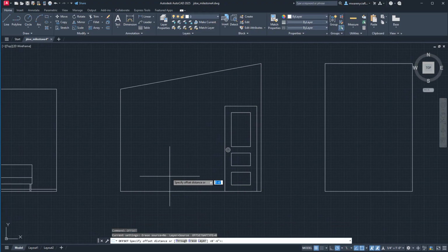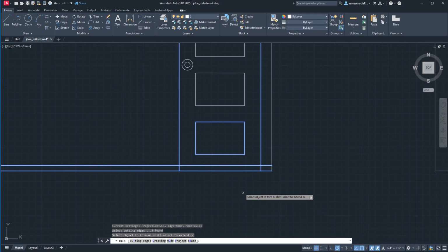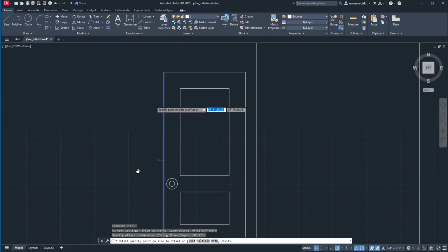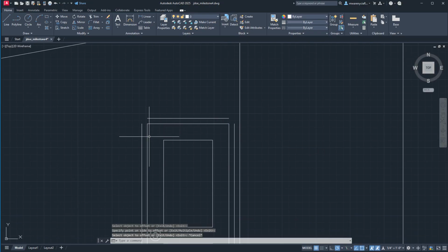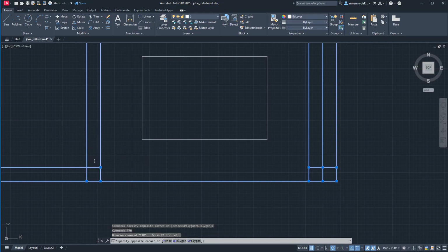Again, I'm going to come over here. I'm going to offset this up 2 inches. This will be our baseboards here. And not going to have it around the door there. And then the door itself gets its own wrap. So we'll do that. And then we'll do a fillet set to radius 0. Didn't do multiple. Okay. So there's a frame around our door, and then one last trim.